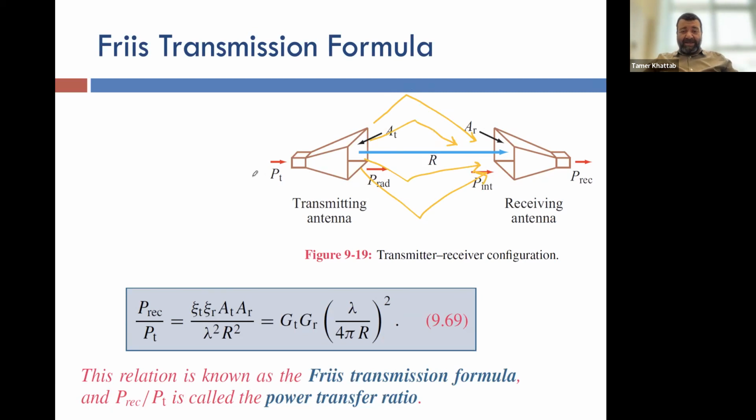Is this good or bad? It can be good if all of these arrive added together with the same phase, or 2 pi phase shifts. But if these electromagnetic waves arrive with phase shifts that cause them to destructively interfere, they will cancel each other. So collectively, the performance is worse.